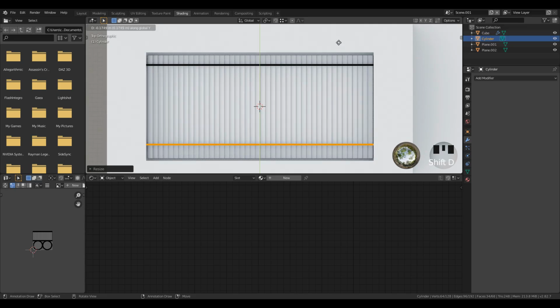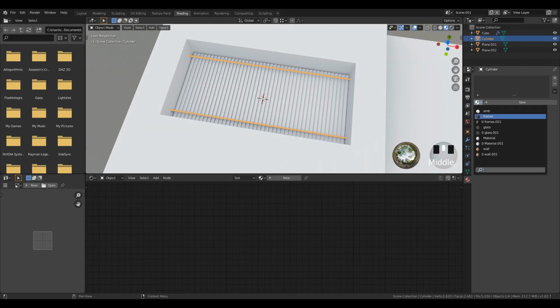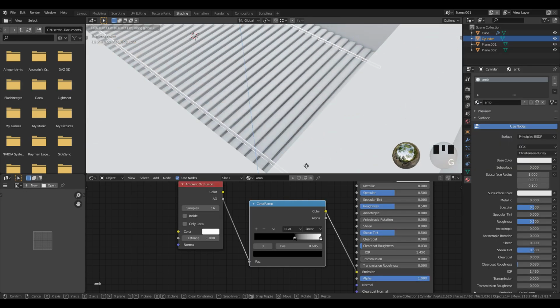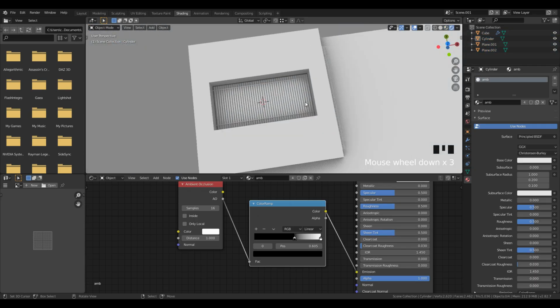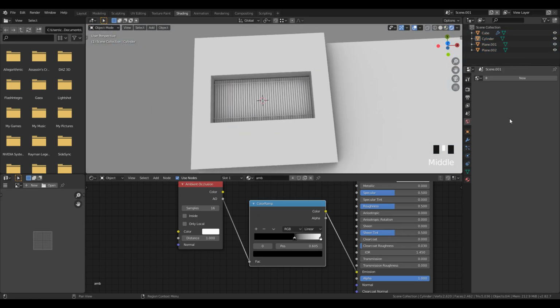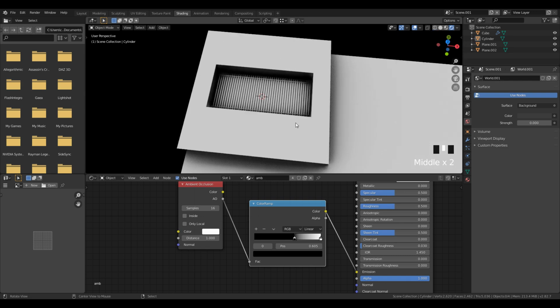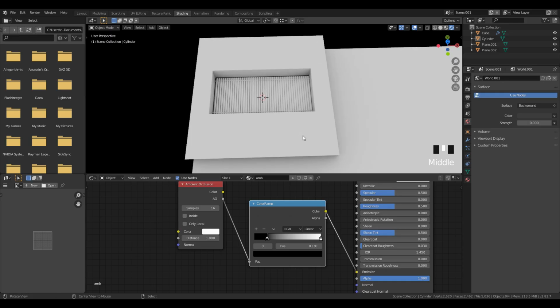After that, add ambient occlusion material to it. Make sure it is closer to the window blind. After that, in the World tab, click New and change the strength value to 0. Then change the position of the black color stop slightly to have slight darkness to it.